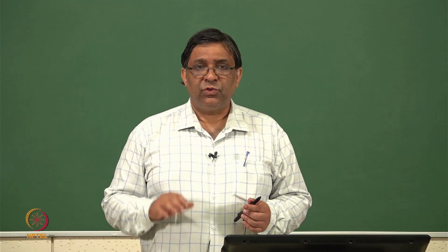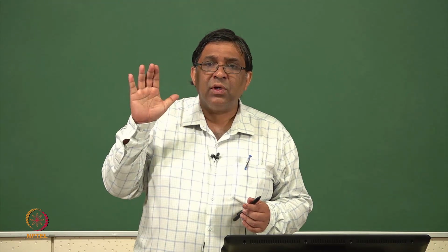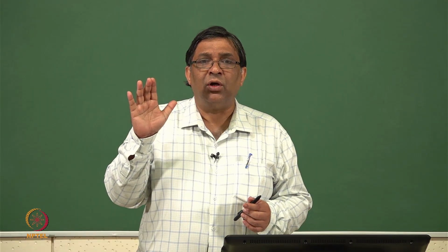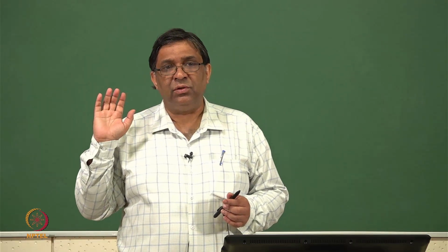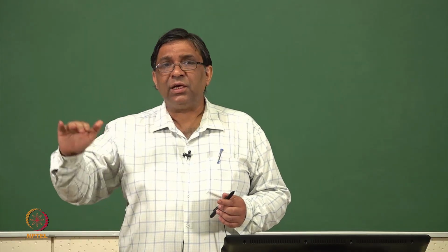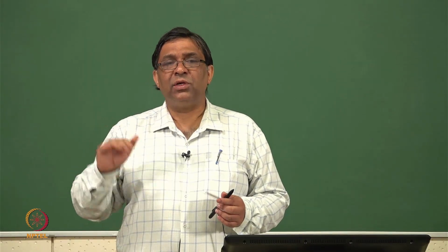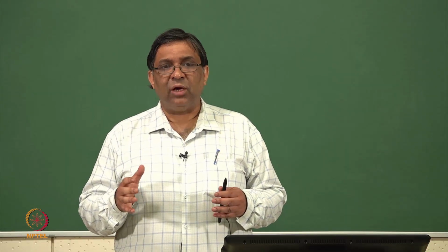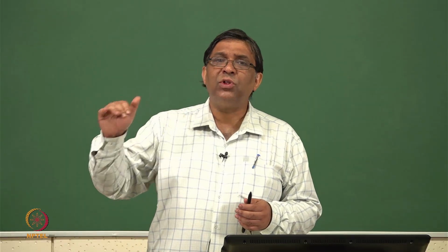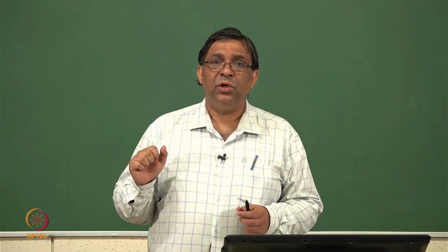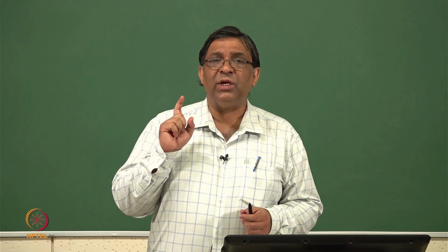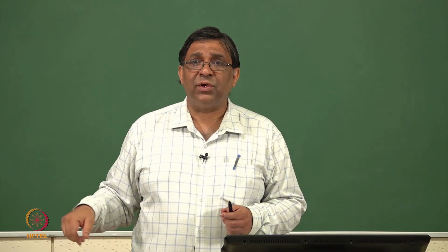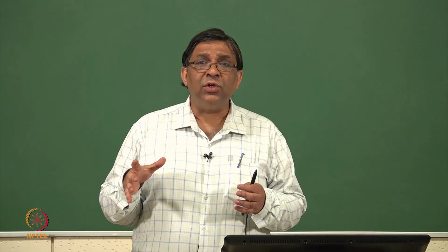So the question is, if you do not have this 100 or 200 micrometer thick silicon, then you do not have enough absorption. Although by texturing you minimize reflection and make absorption more, remember that the more material processing you do, by texturing the front surface or the back surface, the more defects you introduce in the system.